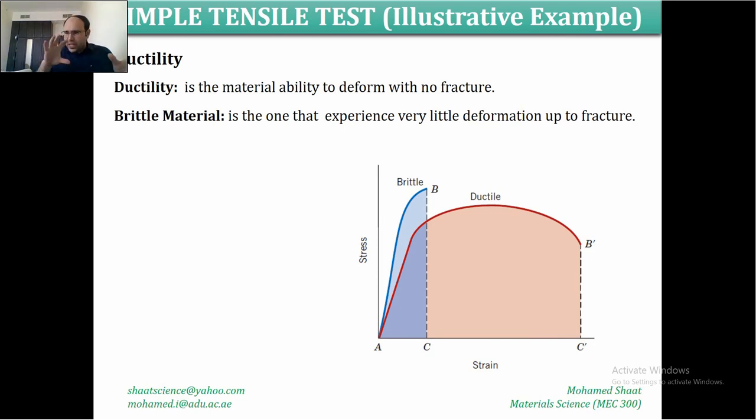very flexible. But flexibility is kind of different than ductility. They are very related, but there is a slight difference between them. So for now you can understand ductility as a very flexible material that can be easily deformed with no fracture. But the other side is the material that is brittle. Brittle material, like the same plate but made of glass.